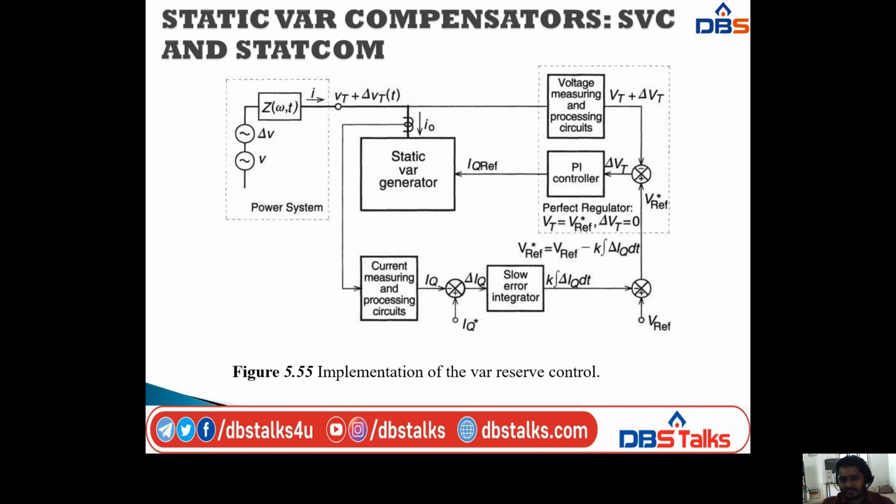It consists of one power system with two generators. One has voltage and the other has change in voltage, and these two are connected to the impedance, which is a function of angular frequency and time. It also connects to the terminal voltage of the power system, that is Vt plus delta Vt of t, and then it is connected to the static generator along with the voltage measuring and processing circuits and this coupling transformer. This is connected to the current measuring and processing circuits.